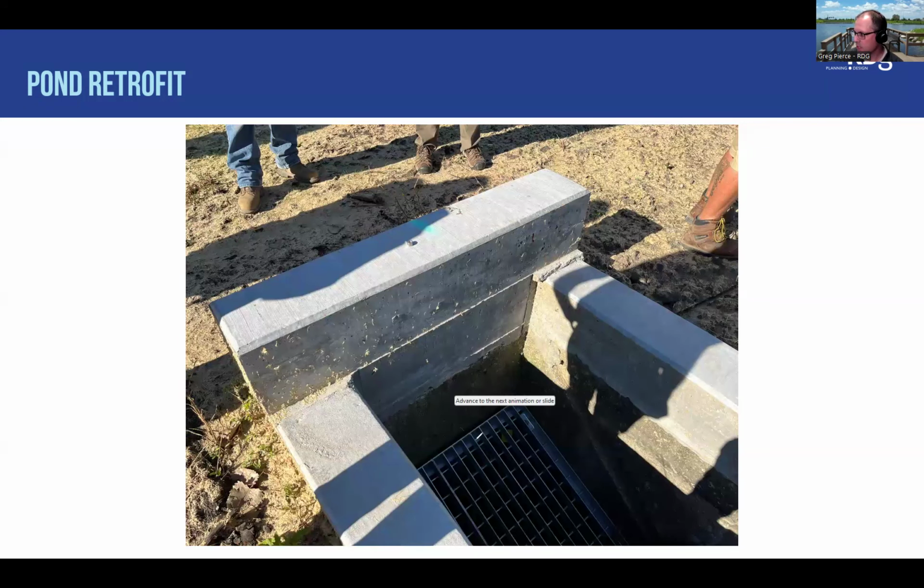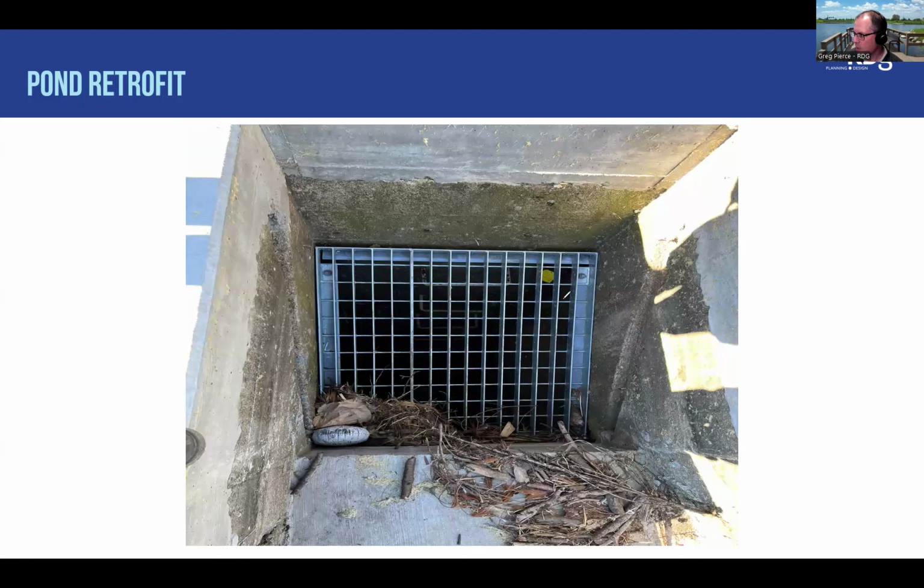And then this is the outlet structure. There was an existing structure there, so we basically just had them cast a little higher wall around a couple of the sides, and then install a new grate here that's on an angle. Here's a picture of that grate. One reason why we placed it at an angle instead of flat is if you start to have debris, the debris will collect on the low side of the grate. So as the water level drops, it'll settle there where you can clean it out. Where if it was placed absolutely flat, it could create a mat which could block flow across the inlet.